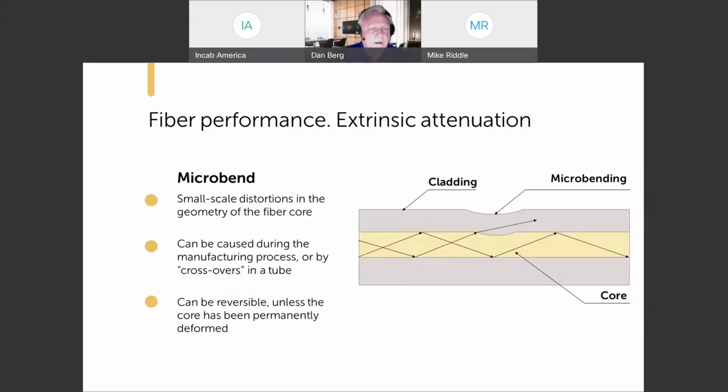There's the microbending. Microbending is a small scale bend or perturbation in the fiber. It's usually a bend less than a millimeter in radius, and it occurs often when pressure is exerted on the fiber from an external source, and also whenever other cable components within the cable press on the optical fiber.